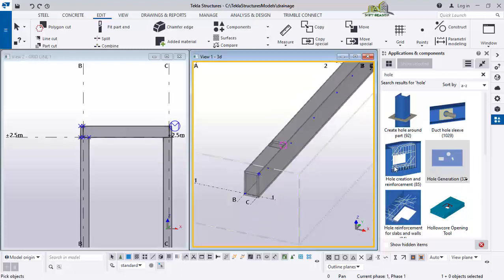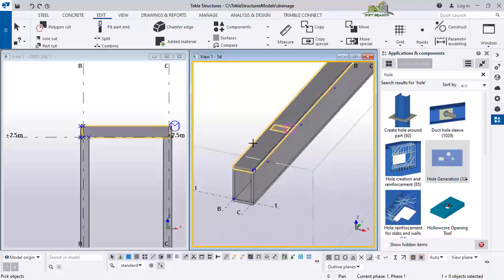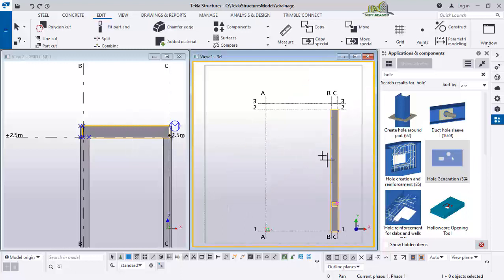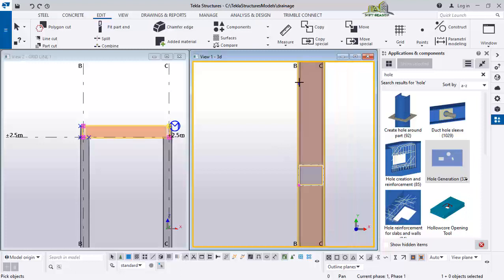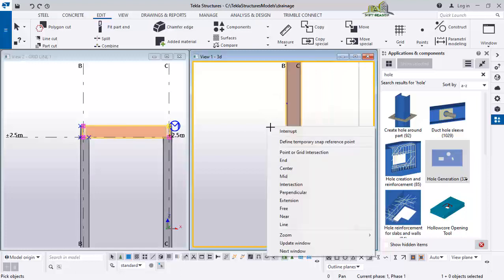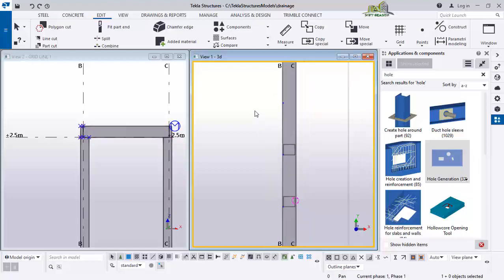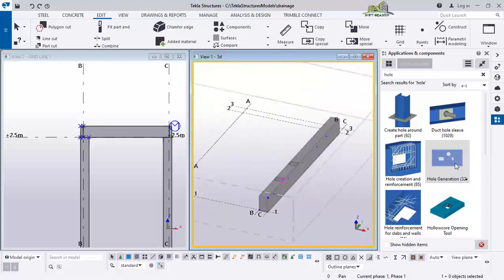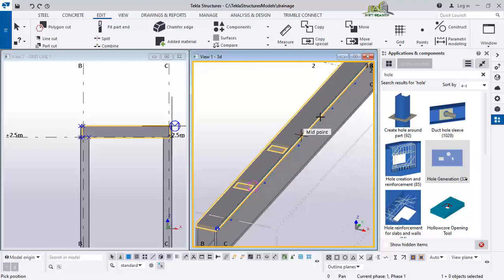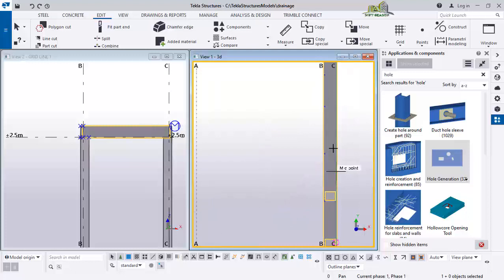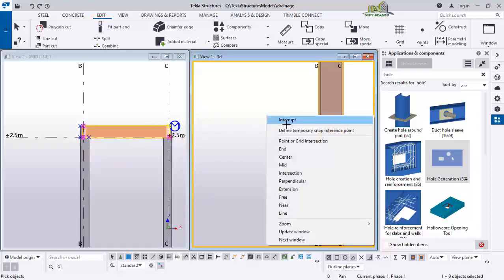Okay, we want to activate this again. Select this slab again, just like this. Click the middle of the mouse or the wheel. Okay, then do Control P to go to the plan view, then pick this point, the third point, to create just the same thing. Okay, we may not be able to continue to pick the point because the command works once for each hole. Okay, so after which you have to interrupt. Okay, go back to the 3D, activate it again, select this, click the middle of the mouse or the wheel, navigate to the plan view, pick this point, right click, interrupt,